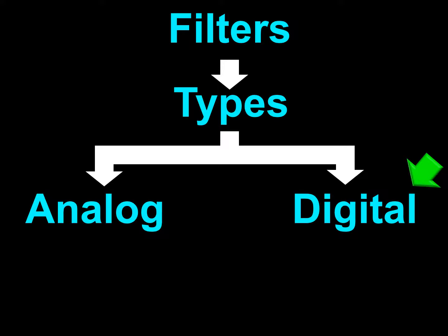And digital filters. Digital filters operate on a discrete sample of the waveform and so require digitalization of the data by an analog to digital converter before filtering operation.